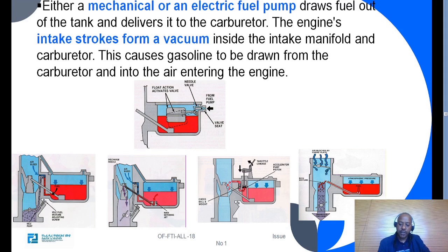In this case, the throttle valve is open, and at this time the main jet supplies the required amount of fuel. So the fuel and air are mixed in this chamber. And in the acceleration case, when the driver depresses the pedal more, the acceleration pump is activated and additional fuel is injected into the chamber through this port.